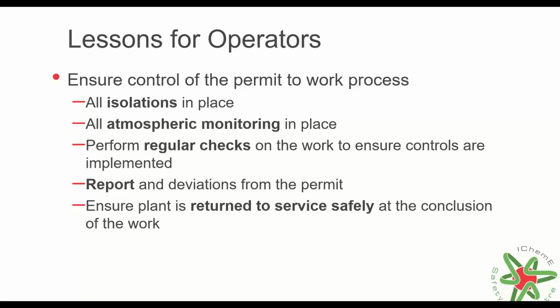And that's a way to really focus on only doing high hazard or hot work when you have absolutely no alternative. We shouldn't just be routinely doing it. It should be a specific thing that we try and avoid wherever we can. And I think for me, that is one of the most significant learnings of managing permit to work and in particular hot work systems in my career.